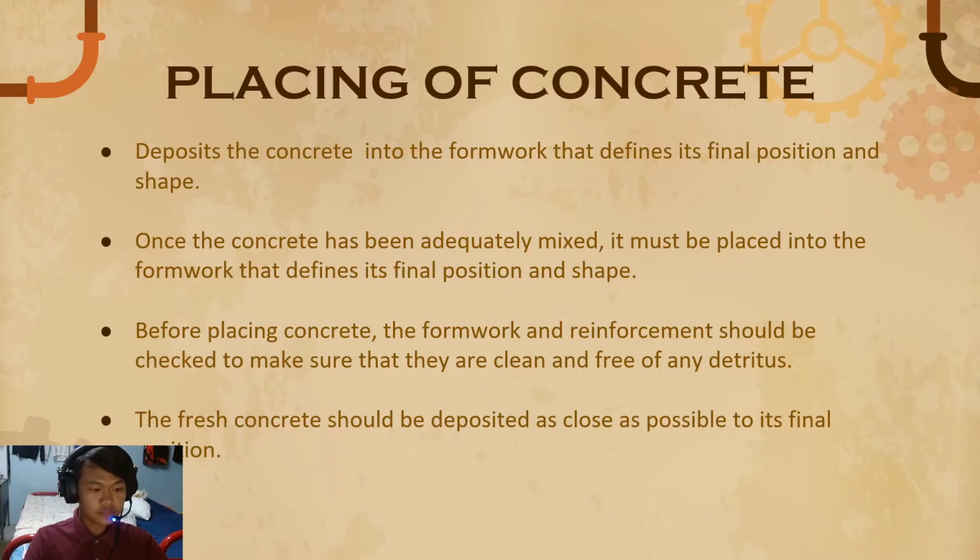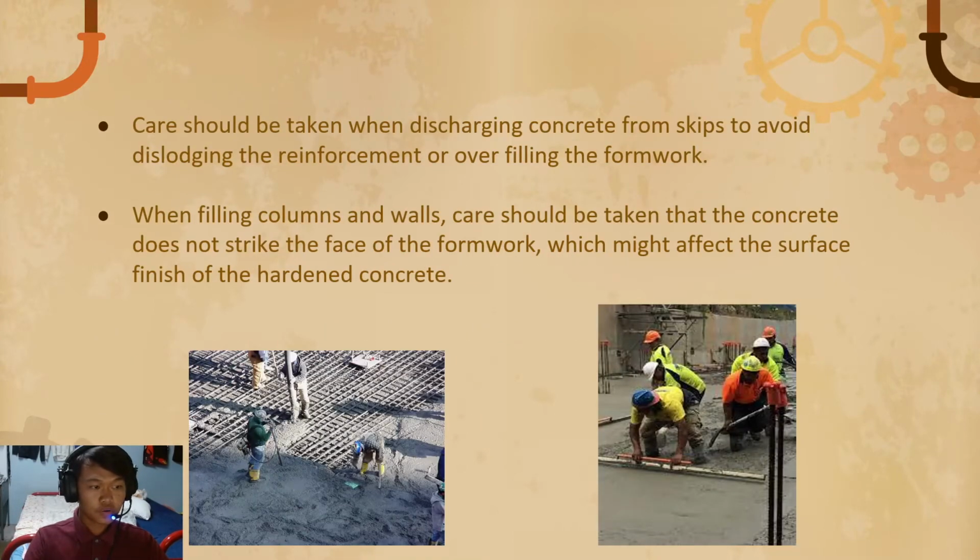Point 4, the fresh concrete should be deposited as close as possible to its final position. Point 5, care should be taken when discharging concrete from the skip to avoid dislodging the reinforcement or overfilling the formwork.